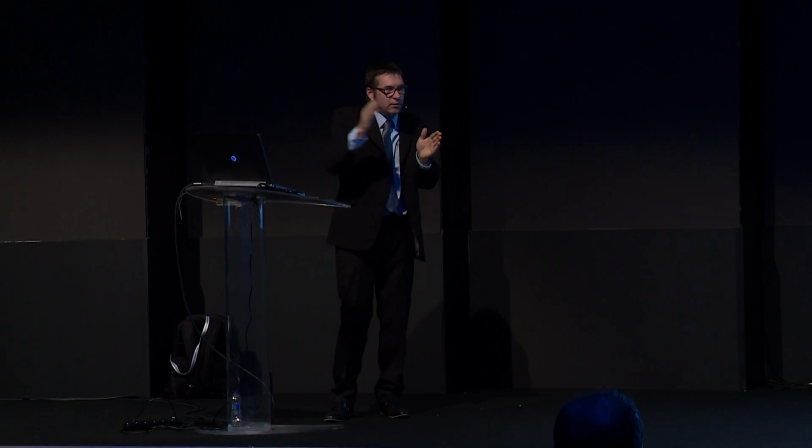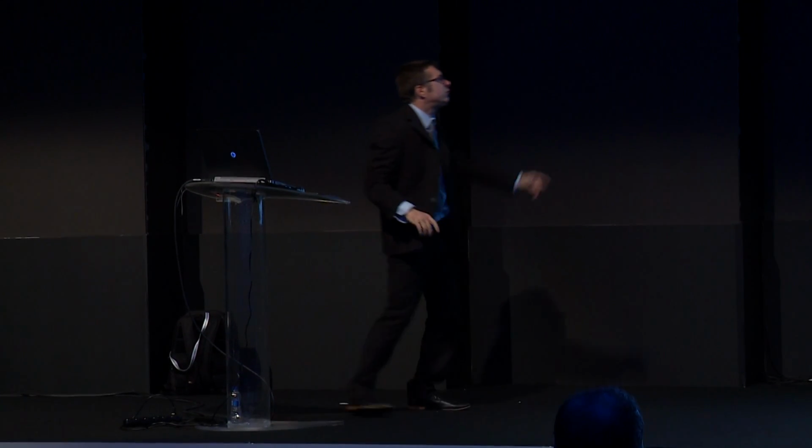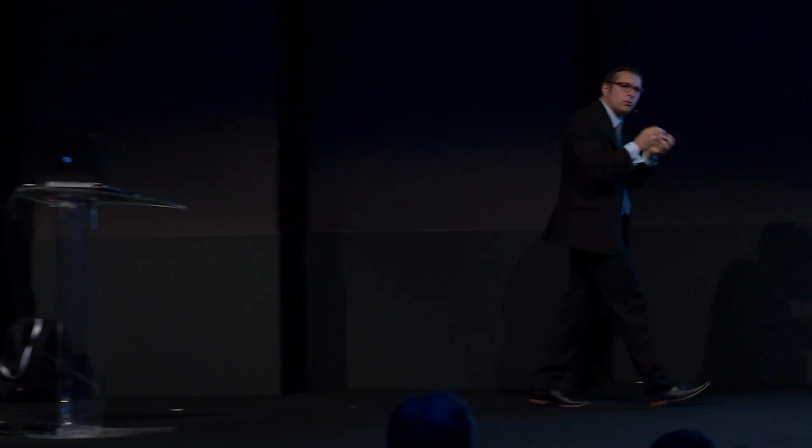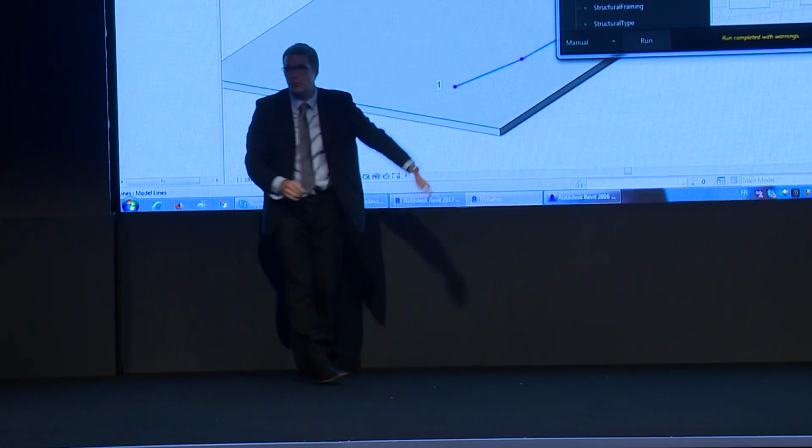And using this code, I use a node called curve point at parameter. That means here it divides my line by these numbers. If I click run, you see here and here, in Revit, there are virtual points. They're not designed in Revit, they're designed in Dynamo.